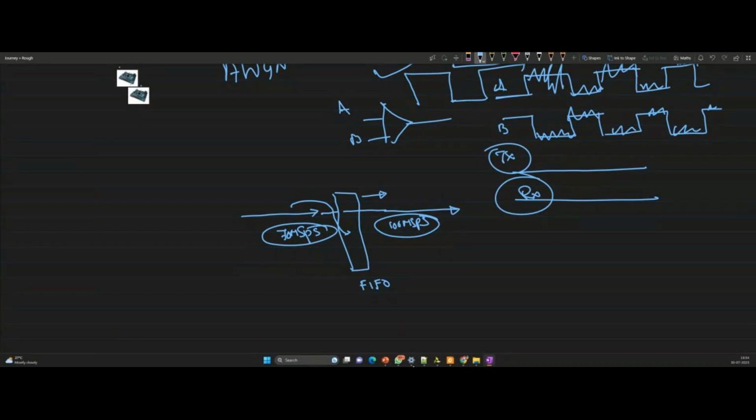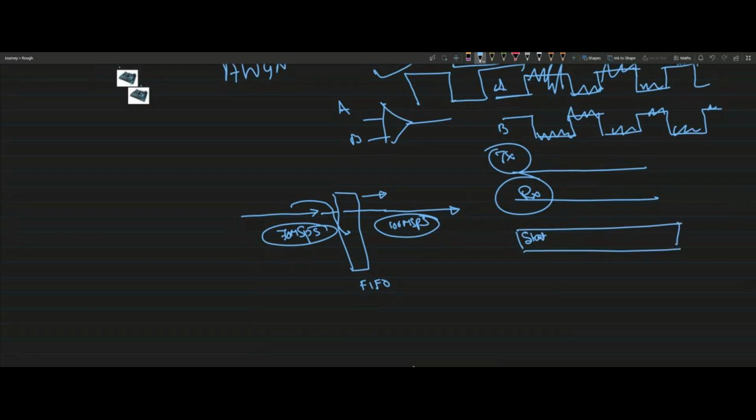Usually, in the format in which we are sending the data, one bit will be the start bit, and we can send 5 to 9 bits of data, and one stop bit will be there. But both sides' clock should be the same. Both receiver and transmitter should know what the clock speed is. Then only can we send over this UART. Along with this start and stop, in between we will have a parity bit.